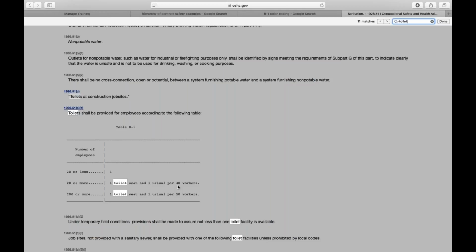So basically, instead of doing two toilets, you can't count a toilet and a urinal in the same box as two. Okay, it's because not two people are going to go in there, right? So basically, when they say a toilet and a urinal, it would be a separate urinal. But the thing is, a lot of times in this, we know we're talking about portalets. So don't consider a portalet with a toilet and a urinal as two. That would be one. Okay.